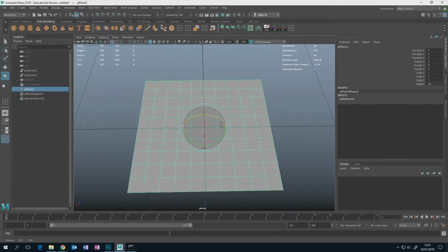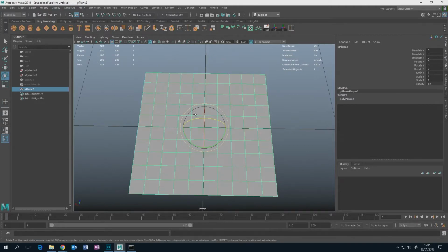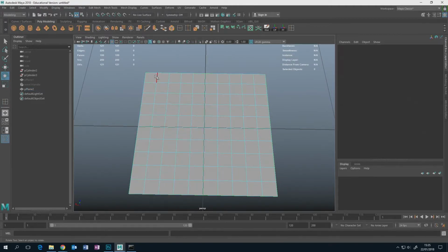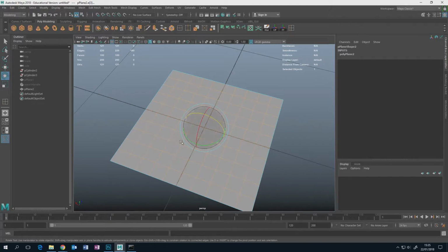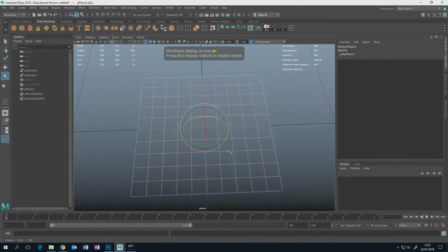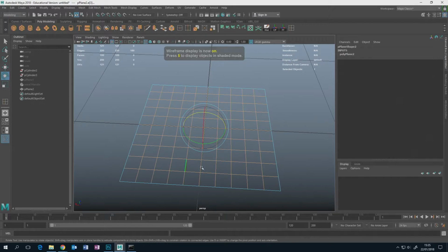So these are nonlinear deformers, right? The most usual way you would use these is you've done some modeling. If you're doing the Mars base, you're modeling some paneling and it's got to be curved, but at the same time it's got to be what they call hard surface modeling. It's got to look sort of manufactured. Trying to model hard surface paneling around corners can be a right pain, and it can be a lot easier if instead you model it all flat and then you use these nonlinear deformers to deform them into shape.